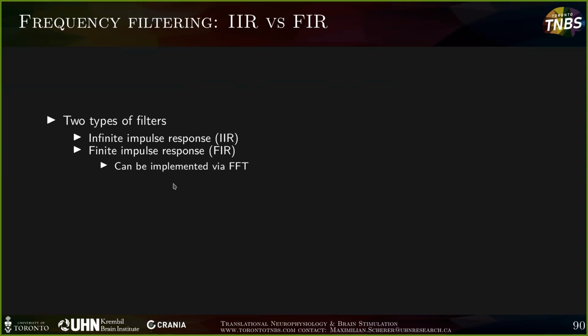And while that may not seem as much of an issue if you look at the difference in amplitude across your EEG signals or EMG signals or whatever, you're going to have a significantly high amplitude line noise and an even more significantly high amplitude deep brain stimulation noise. They are going to be all over the place amplitude wise. So you need a strong suppression, especially if you want to record data from somewhere in the vicinity of those noise sources.